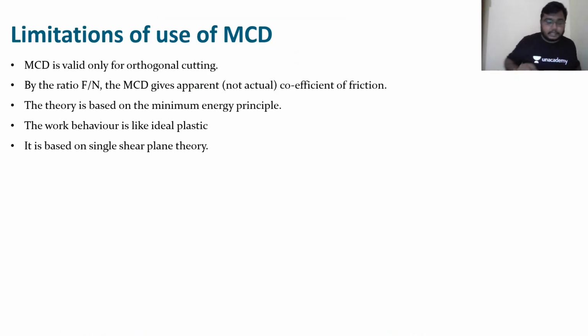Next, what are the limitations to use merchant force circle diagram, sir? Merchant force circle diagram is valid only for orthogonal cutting. When Merchant made this, he was asked, can you draw this circle for oblique cutting? And Merchant said, okay, I failed. For oblique cutting, I cannot draw this because there are a lot of complications.